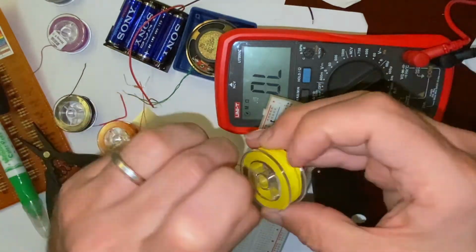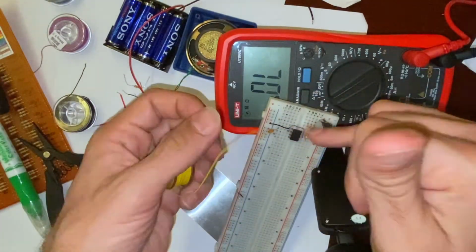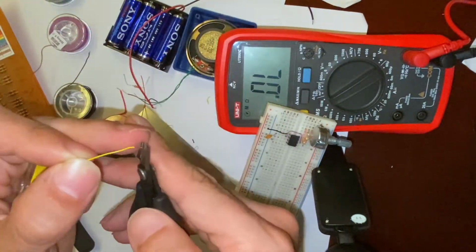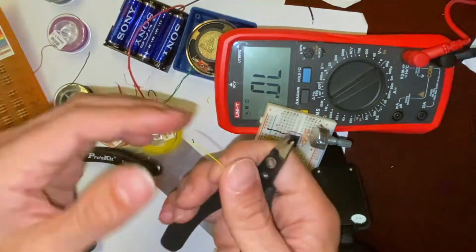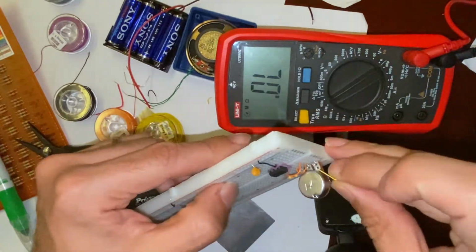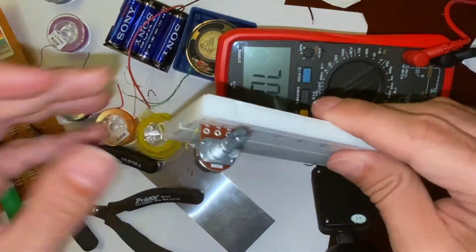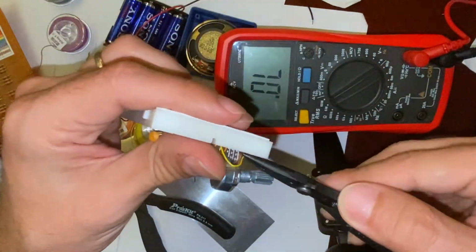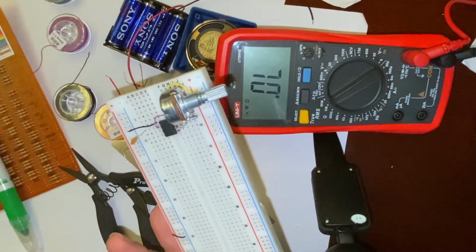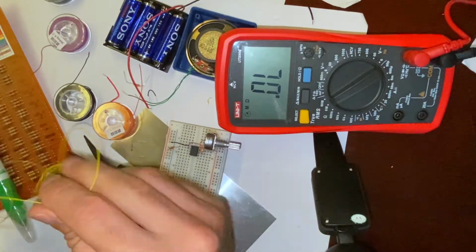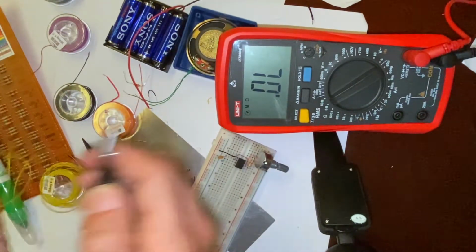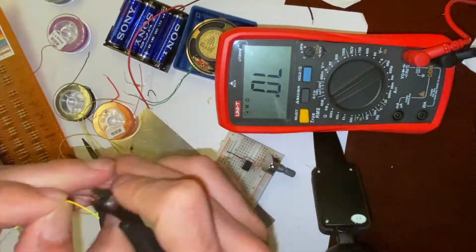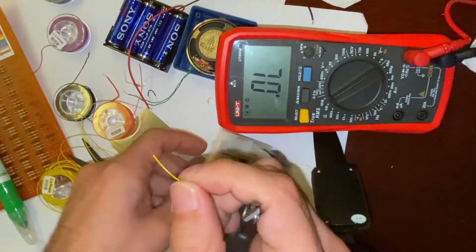I'm sometimes checking with a multimeter that what I think is connected is actually connected, and I'm being careful with the cables. Every time I go on to connect them, I double confirm the position, and I'm trying to use different colors. For example, I use black for ground and yellow for VCC. So these visual aids, when the circuit gets more and more complex, are essential. Otherwise, you get completely confused.